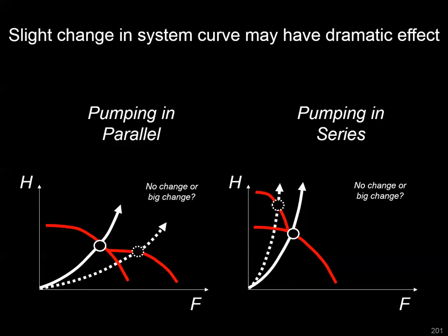But if you just move a little bit to the right there, so if you have a little pressure drop in your system, you're going to see this big change in flow, which is not really the type of operation we want to have out of our pumping systems.